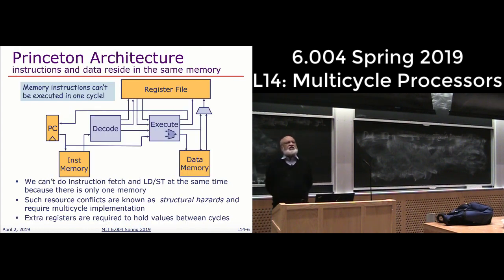All right, so what is the Princeton architecture? The Princeton architecture is we take this Harvard architecture, but we store them in the same memory. So we bring these memories together. Why? Because one of the biggest advances in computing, without which we couldn't have gotten off the ground, was the fact that you can do arithmetic on instructions the same way as you operate on data. This was so important. Without that, in the beginning, people could not have written any code on the first generation machines that were built in the 40s and early 50s.